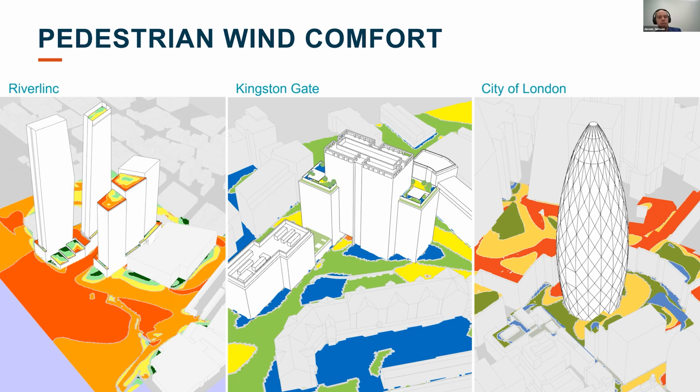So you would really look at 1.5 meters above your ground level, plus roof terraces, running 16 directions around the windrose, or 36 or whatever, and then comparing those 16 results with the windrose, and you can then look at how windy is it in these locations over the year, and are these spots comfortable for long-term seating, your restaurant terraces, that sort of thing, to standing, entrances, walking, up to uncomfortable. So these are a few of those projects that we've done in that respect.